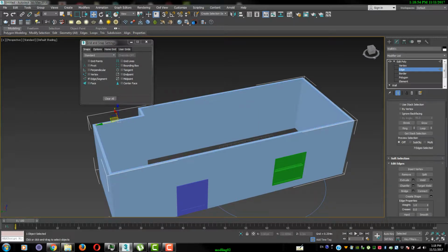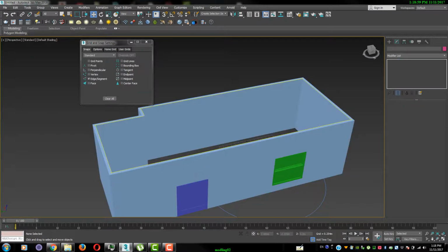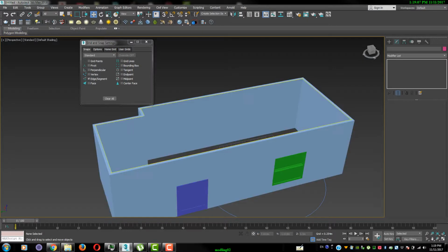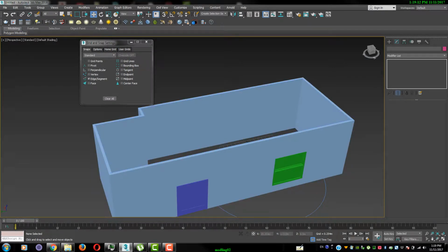Okay. I turn off the edge selection. I select my edge. If it is too hard for you to select your 2D shape, because it's difficult to see, we have a selection filter in 3ds Max. So I tell it I want shapes. So now the mouse doesn't feel any 3D, it just feels 2D.